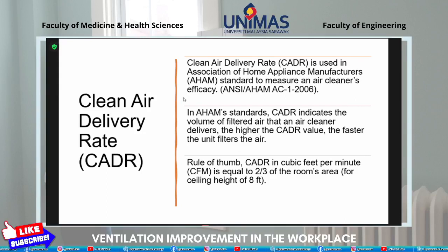Okay. So basically, in AHAM standard, CADR indicates the volume of filtered air that the air cleaner delivers to actually clean the air. So the higher the CADR value, the faster the unit filters the air. For example, if you remember the hospital ward case just now, it can actually clean the aerosol in 5.5 minutes. 99% of that can be cleaned within 5.5 minutes with an air cleaner of 12 times the room size. 12 times bigger, meaning 12 times the capability of filtering the air in 1 hour.